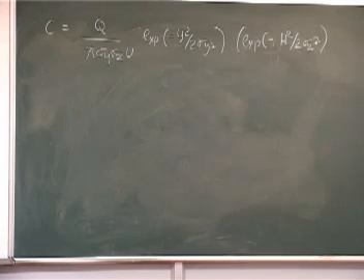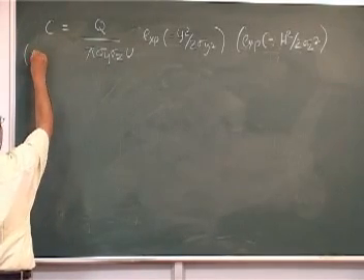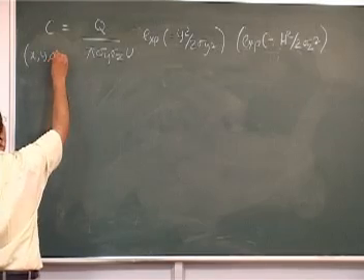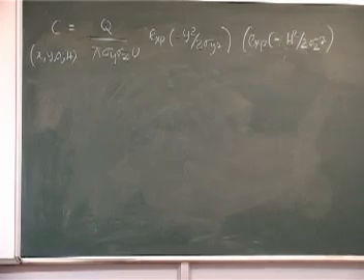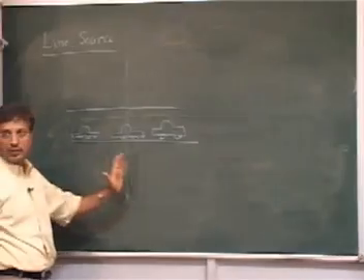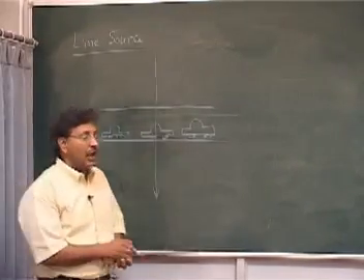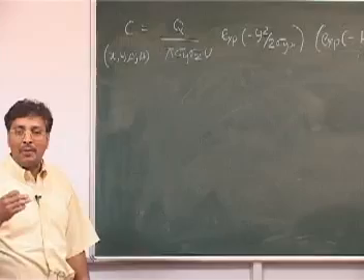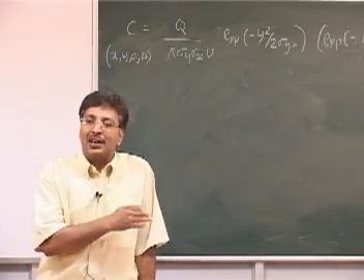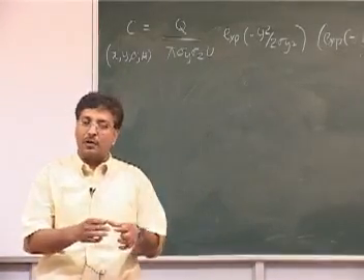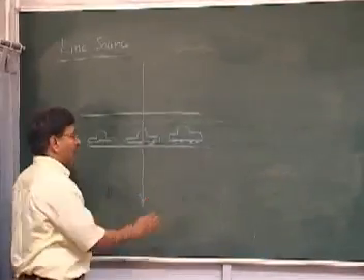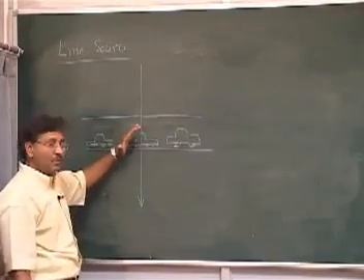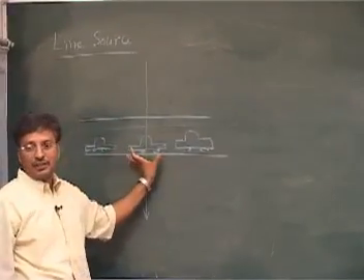So let's say x, y, 0 coming from a height of h. When you have the infinitely long source, you want to define your emission rate Q in terms of mass per unit time per unit length, because there you had the one point source. Here you want to say what is your emission in terms of the mass per unit time per meter.